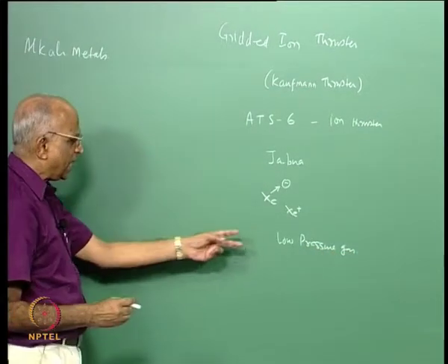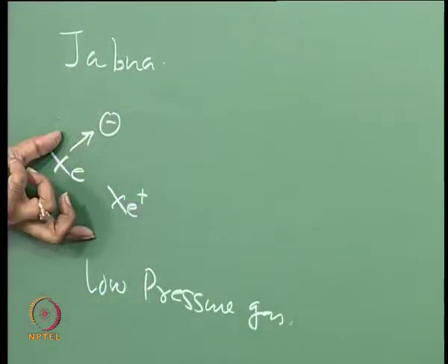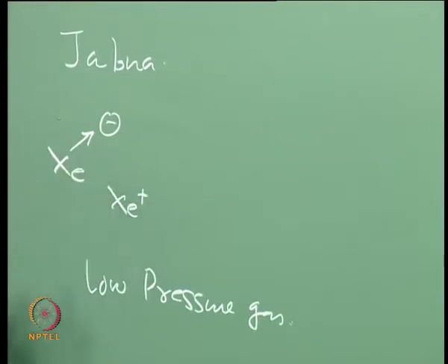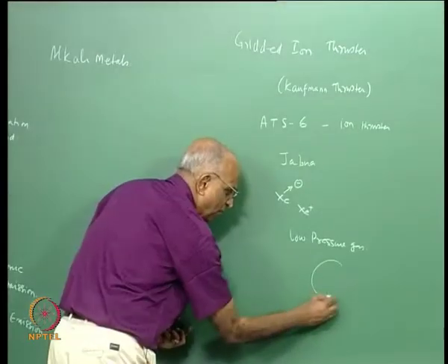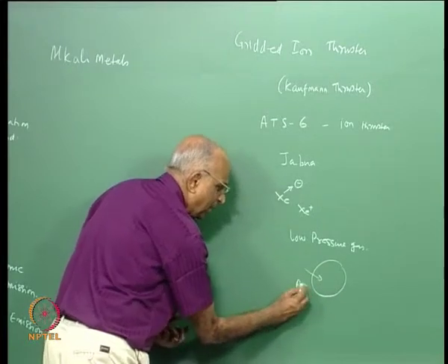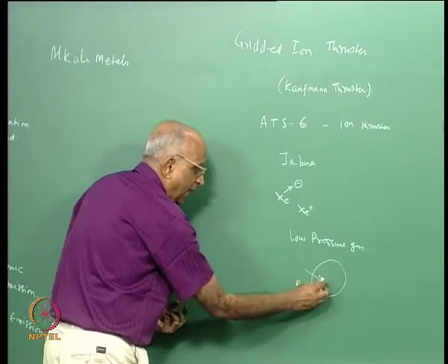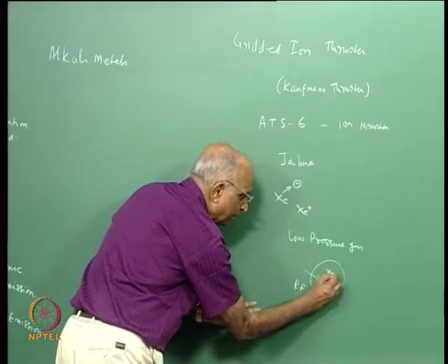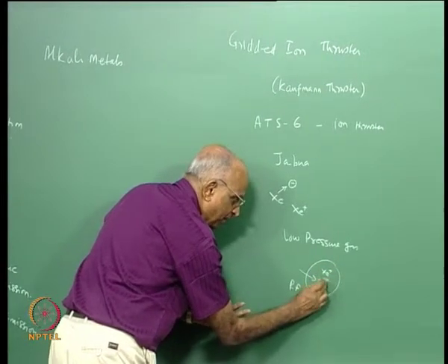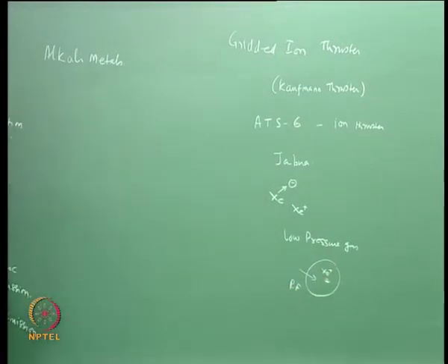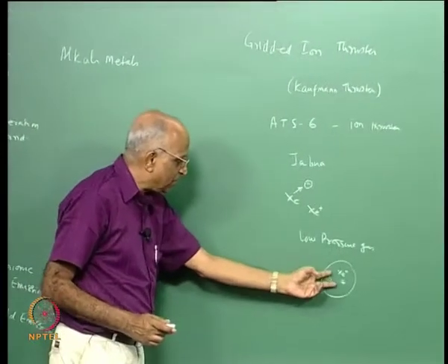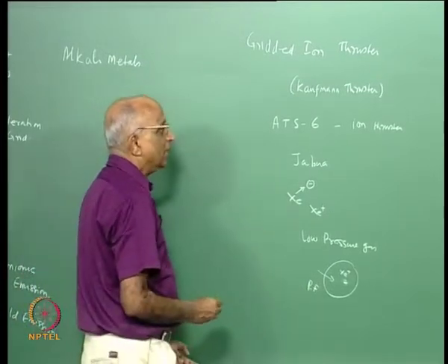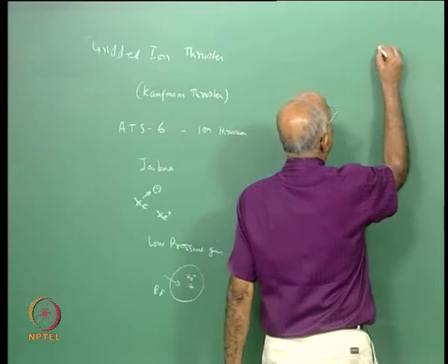and into this low pressure gas, supposing I were to heat the gas. And how do I heat the gas? I sort of oscillate something, like I put radio frequencies in it. I have a volume of gas, I put radio frequency into it, I excite the gas and heat it, and when I heat it, gases like xenon tend to form positive ions and negative electrons, and I use the same attractive forces. In other words, I use radio frequencies also to generate positive charges, and if I use radio frequency, the thruster is known as a radio frequency ion thruster.